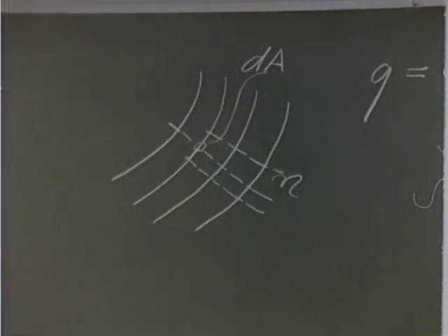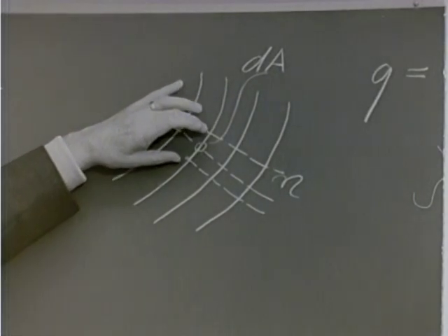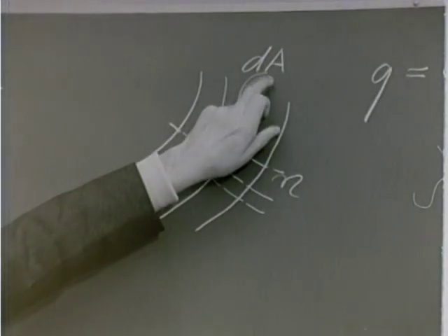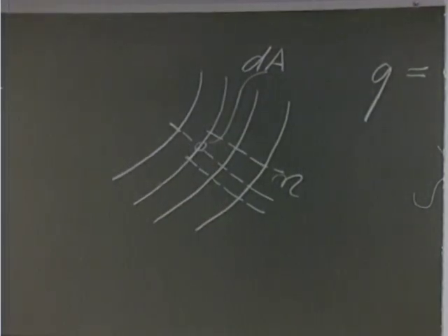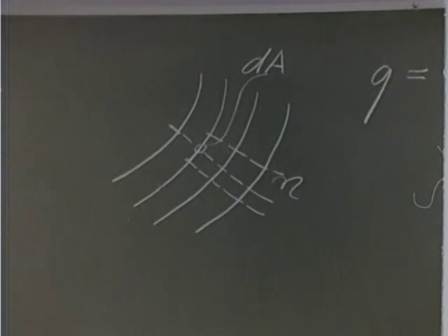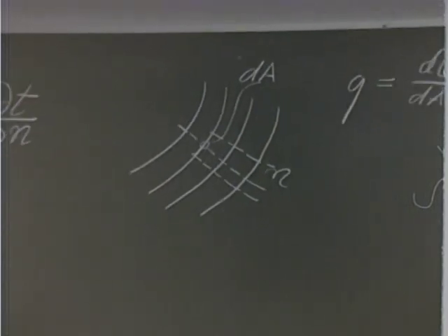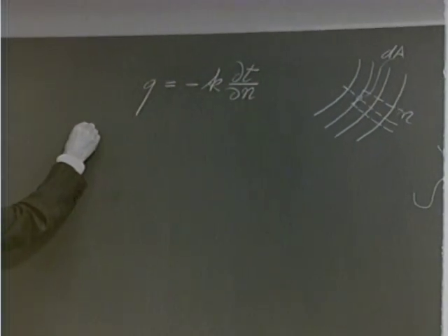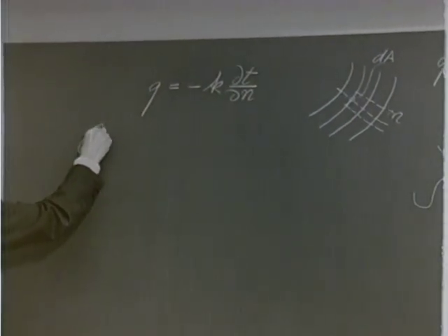In this way we have a stream tube, and again, to get a local consideration, we make the width of our stream tube very small, so we use an area element to construct it. Now I will draw this stream tube once more. Maybe I draw the area element dA in perspective, so that it is clearer.